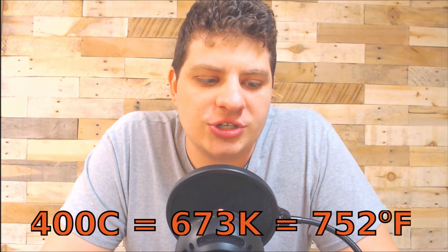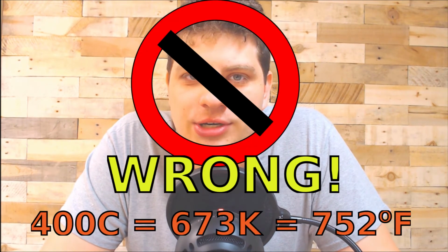The combustion temperature is based on a number of things. First of all, it's based on the type of fuel that we're using. It's also based on the quantity of fuel we're using and the quantity of air we provide. Now, I had a really hard time trying to figure out what temperature the isopropyl alcohol would burn at. From my research, the best I could find is that sitting in an open dish burning, it'll burn at about 400 C, which is 673 degrees Kelvin.